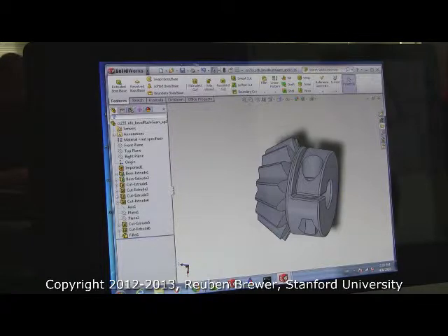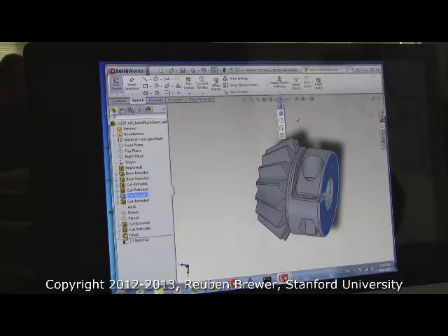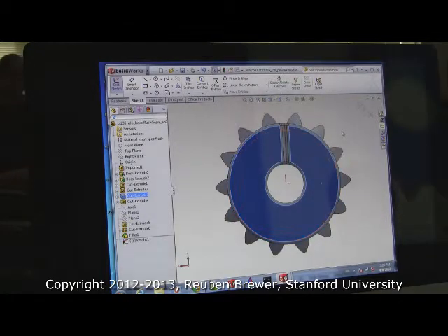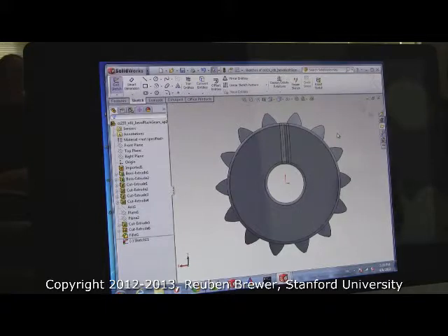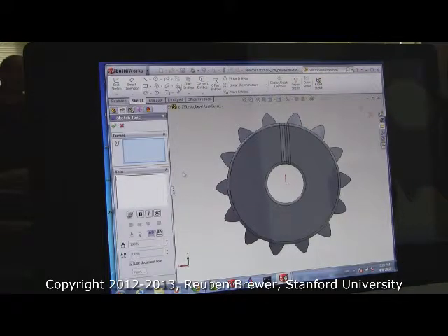Okay, the last step for this part, select this face and cut. So we need some way of differentiating all of these parts from each other when they're 3D printed. So we're going to put our initials in it. See the giant A here? That's for text. Press the A, type in your initials. And then if you click a different point on the screen, it'll move the text around.